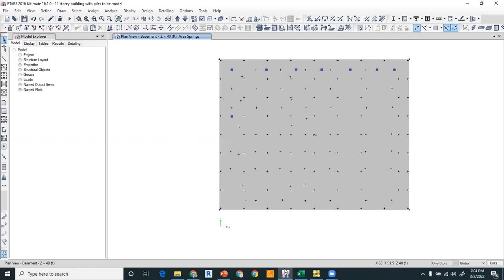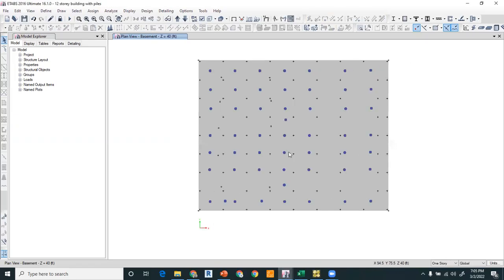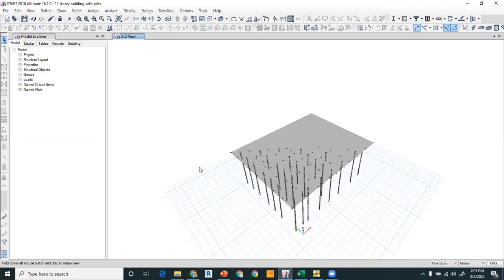So what I have analyzed is the 36-inch, and you can increase this value to 42 because 42 will work, which we have seen in the previous session that 42 was enough and 36 was not enough for the punching check, right?